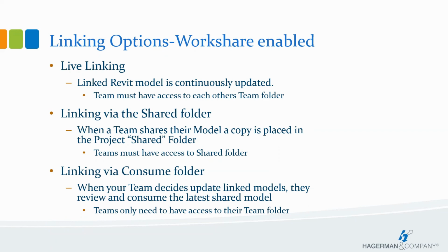When changes are made to a model that is linked into a team's host model, the changes are updated automatically when the host is reopened or a reload is performed on that linked model. With this option, all teams would need at least viewing rights to each other's team folder, which may not be ideal.